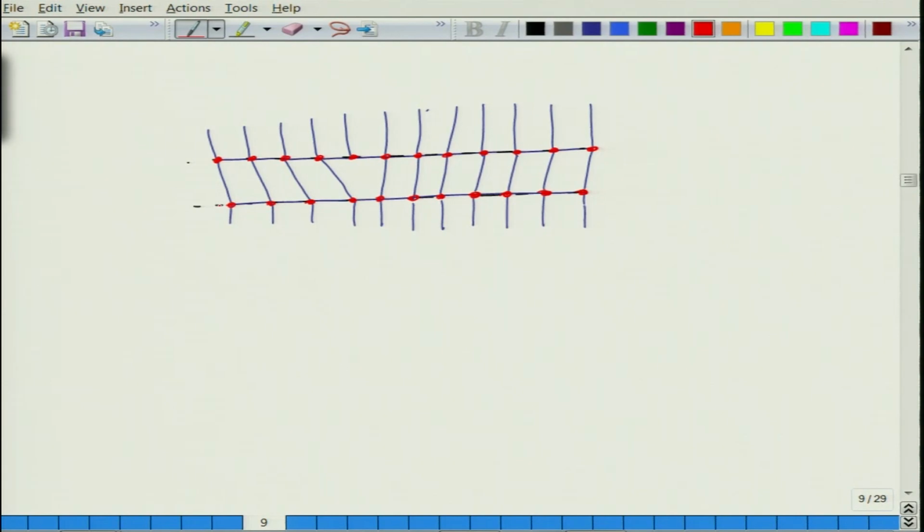The dislocation width is a function of bonding first of all, and dislocation width is essentially the region up to which you can see the distortion. So this is roughly the dislocation width. This is the dislocation, and the core of dislocation. Up to the point wherever the stress field of the dislocation extends, this is the width of dislocation W.